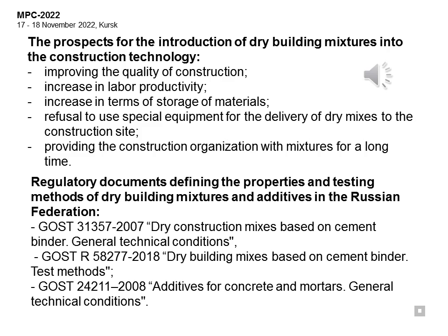Experimental studies have shown the preference for using compositions that contain from 3 to 6 parts by weight of sodium sulfate and from 6.5 to 13 parts by weight of the dispersible powder by weight of the cement.